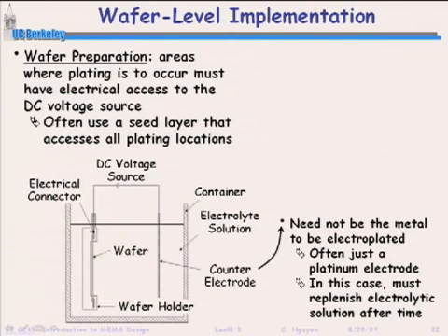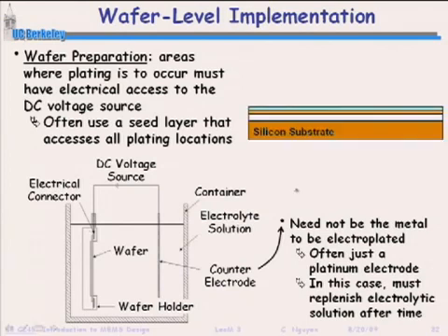The way that you do this is you start with a silicon substrate. You may put down a dielectric layer, a couple dielectric layers, maybe put down through sputtering some kind of interconnect layer that you pattern. Then you can sputter some aluminum on top of this too, or electroplate that aluminum. Cut into that aluminum using an etch that we'll talk about shortly, and then do this electroplating here.